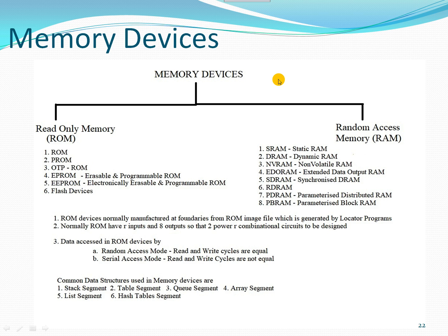Using those tool chains, we convert a higher level language program into a binary program. That binary program is compiled as one ROM image. That ROM image file has to be ported into one ROM device, so that we can use that particular program for the software purposes.